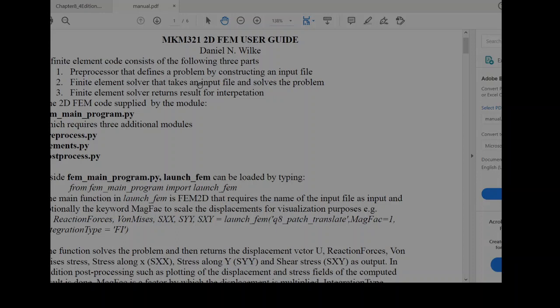Done. You can check any of the CFD that you've done in MW323, any of the MKM that you've done, finite elements that you've done in 323. It's always got that. Let's pre-process, set up a problem, solve, wait a while, post-process, interpret. Okay, that's really the workflow. Okay, these are the steps that you would follow for a finite element program.